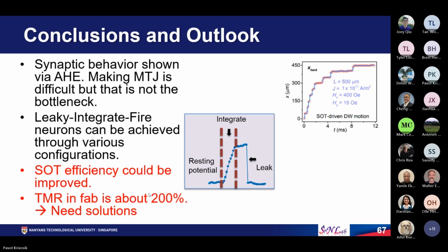Secondly, this is one area of weakness of our devices compared to, say, resistive random access memory or other devices, where they have a huge change in the resistance state between low and high level. So they can achieve many weight levels, but with our devices, we may have maybe 8 states. If you have, say, 10,000 ohms in the parallel state and 30,000 ohms in the anti-parallel state, we may have like 8 different weights. That's possible. But if we can increase this, I know it's very challenging, but this will be very good. So with this conclusion and outlook, let me end my presentation.